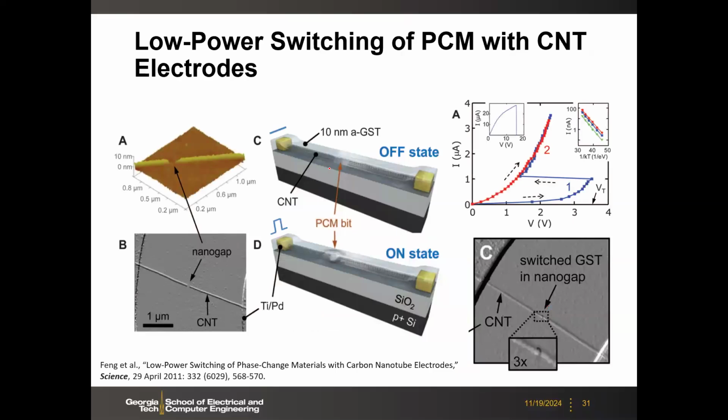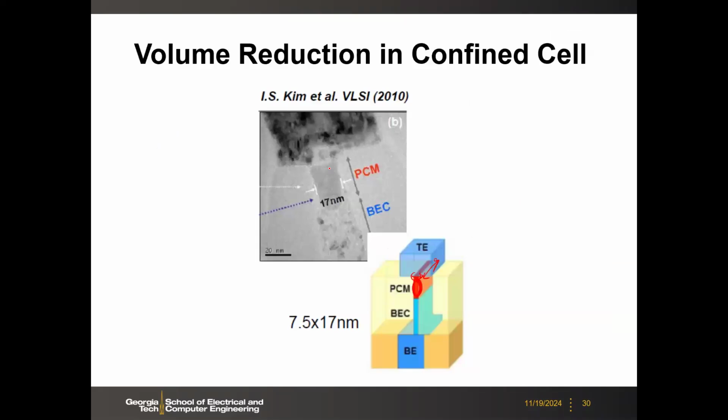Then the research community even did some experiments to look at the ultimately scaled device. Here, you still need some advanced lithography to define this region and then do the etch and so on. Industry can do that, but at a university it is difficult, almost impossible, to pattern 7 nanometer.